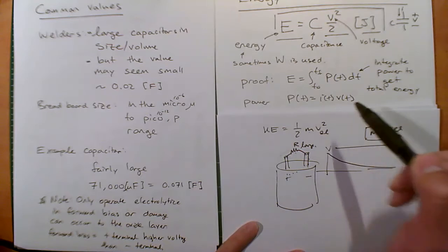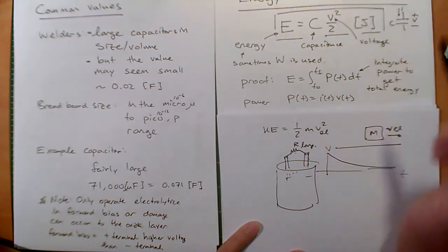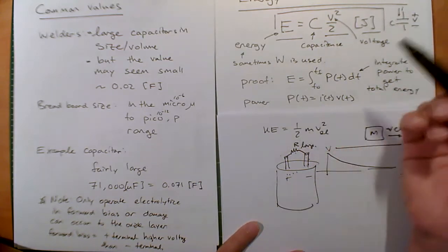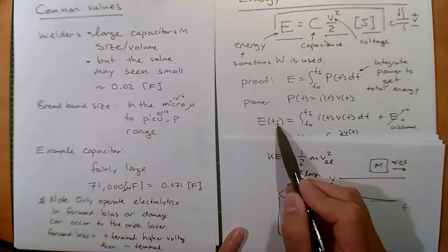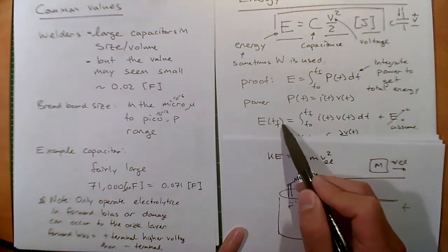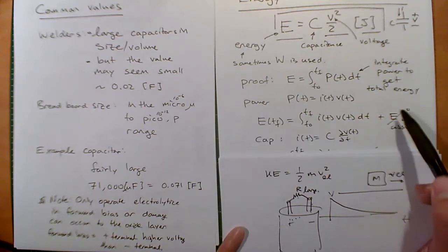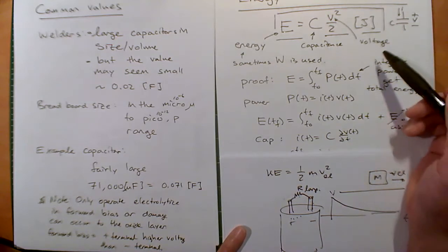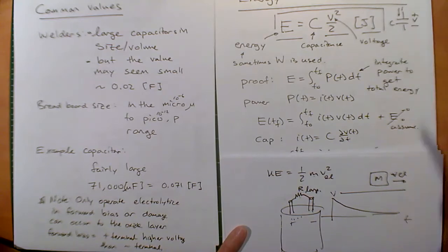Power equals IV, and that works for any element. Let's assume positive in this case because I have the current going into the positive terminal. So if I know the current and voltage, I know the power. If I integrate that power over time, then I would know the energy. And so just like before, energy at the final time minus the energy initial, which I just put on this side, equals this integration. And let's assume that we started out with zero energy, zero voltage on this. And then we wanted to figure out what is the energy at a certain final voltage.